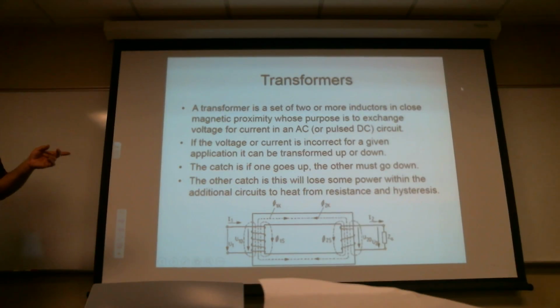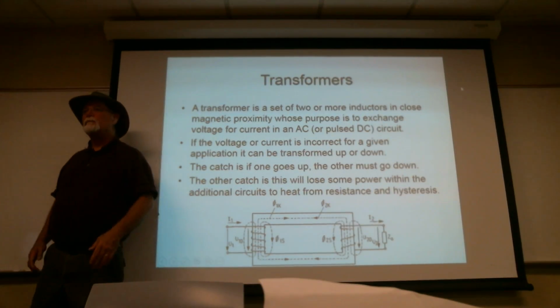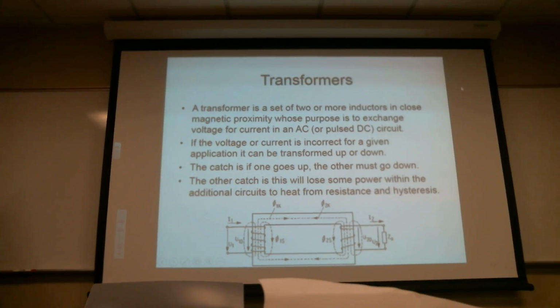So another reason to use this may be if I'm intentionally trying to phase shift one of the phases, I could use a transformer just for the sake of doing that, if that's a goal that I'm trying to accomplish. So again, you will lose a little, but they're usually pretty 99% efficient. They're pretty good.